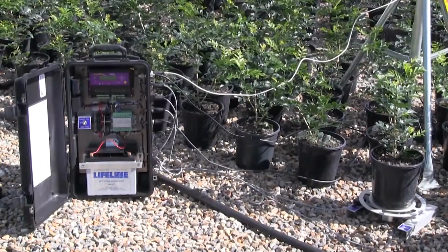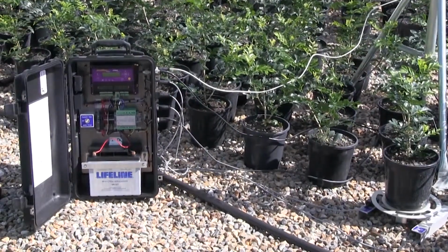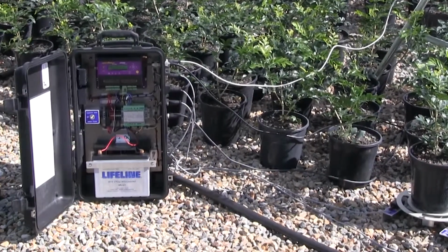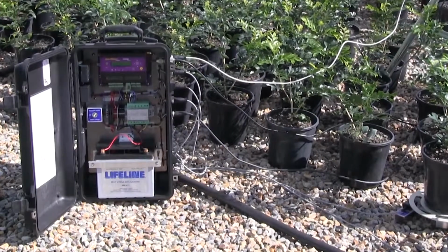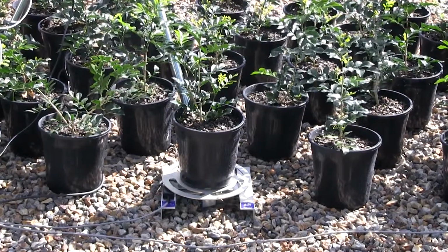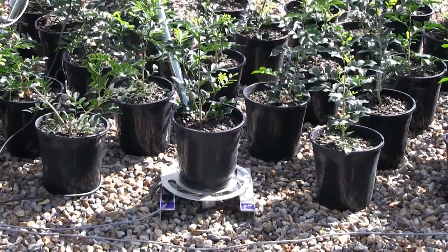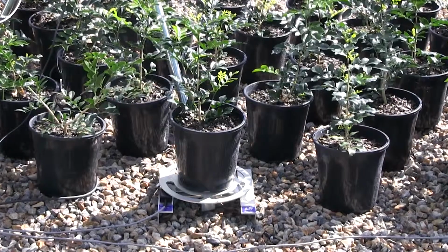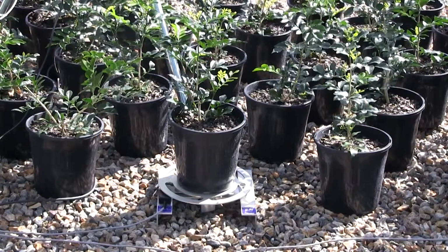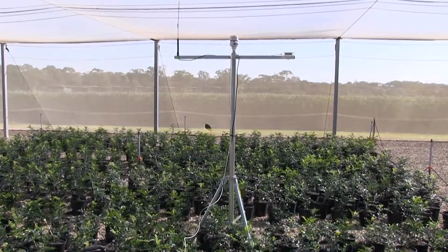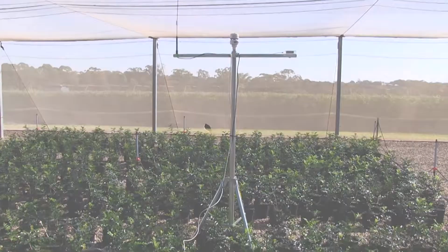The portable weight-based scheduling unit consists of 3 components. A data logger that records the weight of a plant in its container every minute so we can track the changes over time. A load cell is a weighing device that containers are secured to, to track the container weight variations. The data is collected and logged every minute over the time that the unit is installed on a site. The third component is a weather station that gathers information on environmental conditions to help with interpretation of the results.